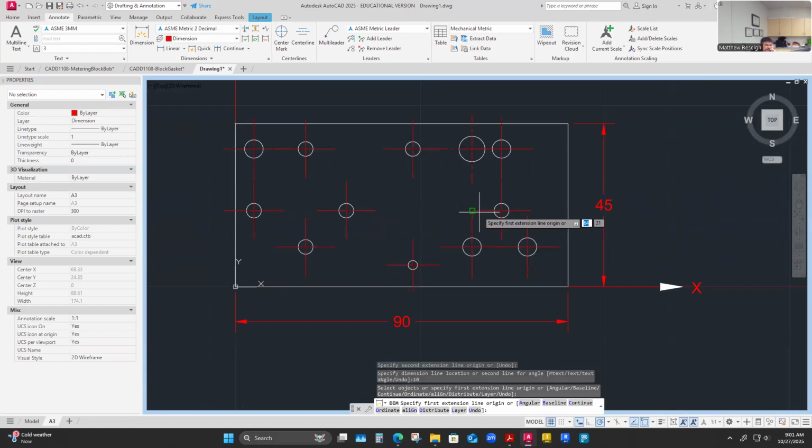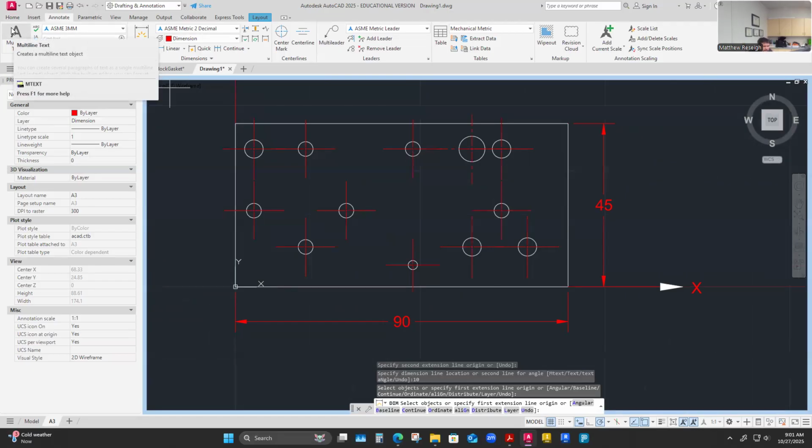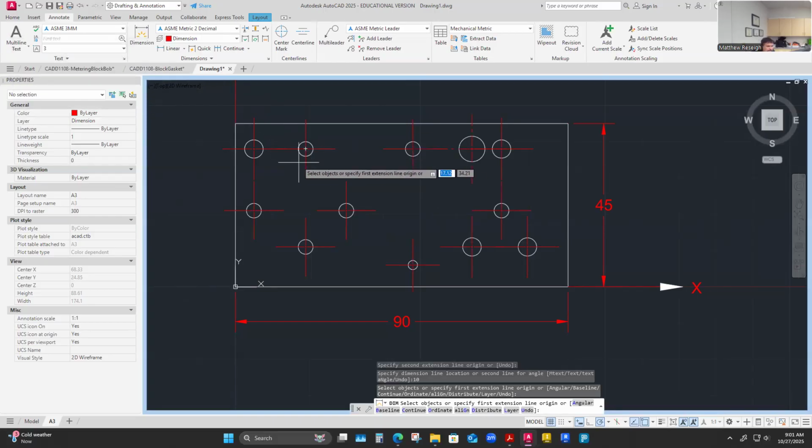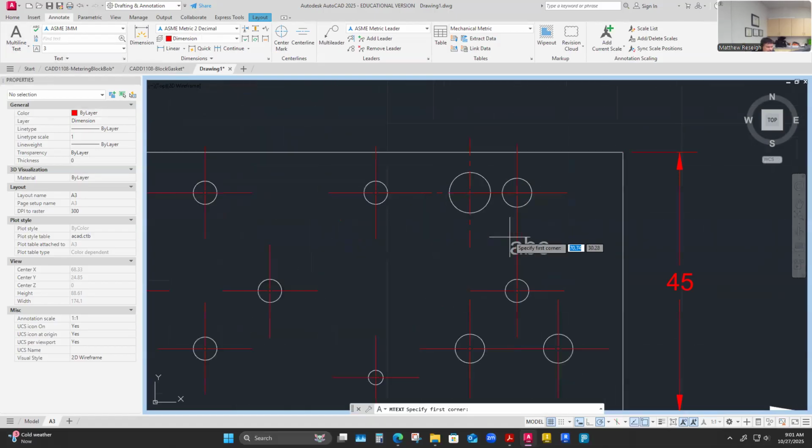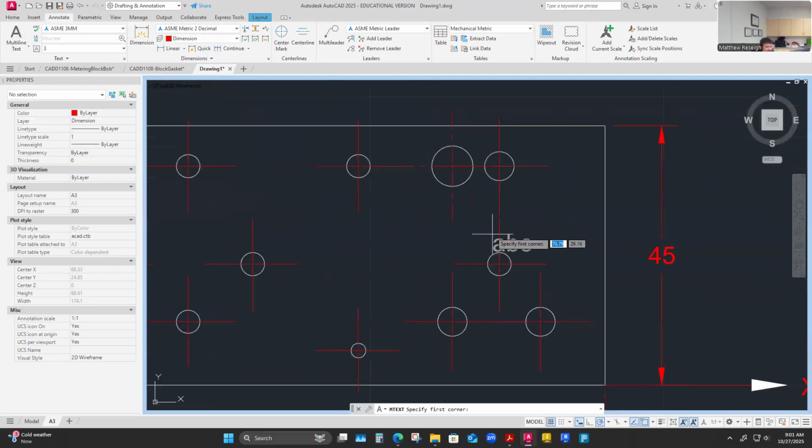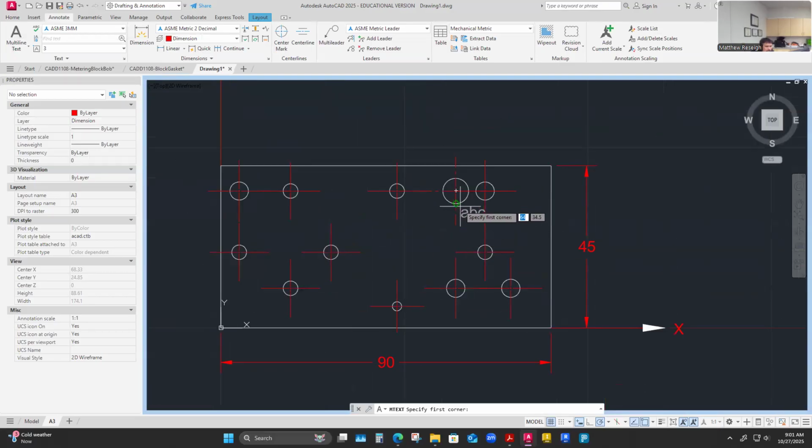So I can follow that. But really, these I can invent myself. I could see that some people's table might be slightly different than mine, depending on how they chose to start their table, and it wouldn't really matter. What I mean is, as a drafter, if you were starting from scratch with nobody to help you at all, you'd be like, well, I'll just start with, maybe I'll label mine largest hole to smallest hole. There might be a systematic approach to how I build my table, because I would try to group things that are together, knowing that I had two odd hole sizes, and four of one hole size and six of the other.